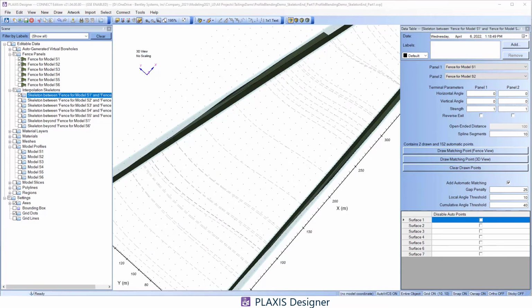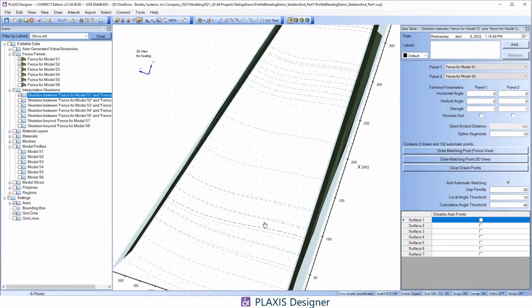Another thing I want to mention is that the splines are automatically created, and unfortunately you can't manually draw them in arbitrary shapes for technical reasons. But that being said, you can influence them quite a bit in the way they connect between the two cross sections. The default that you can see is that they exit each cross section orthogonal to it at a 90-degree angle, and you can see that here on the display.